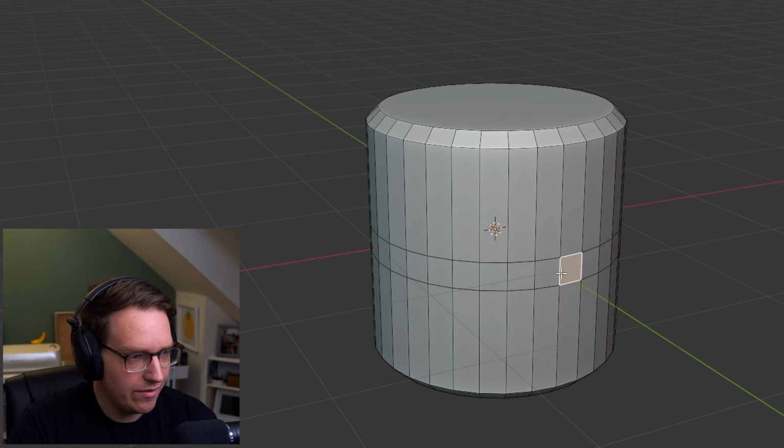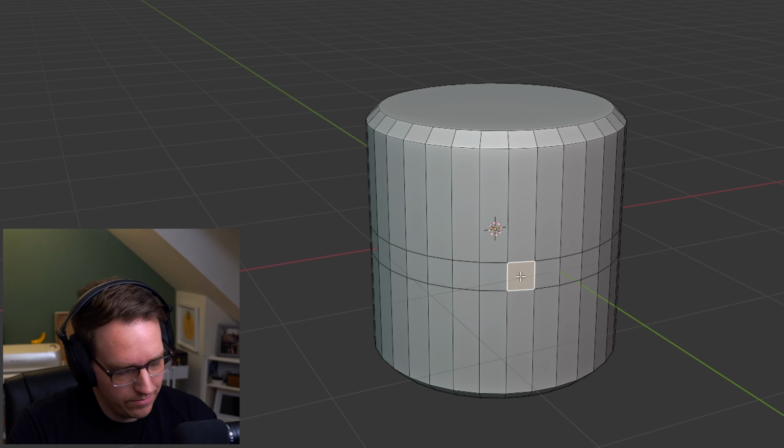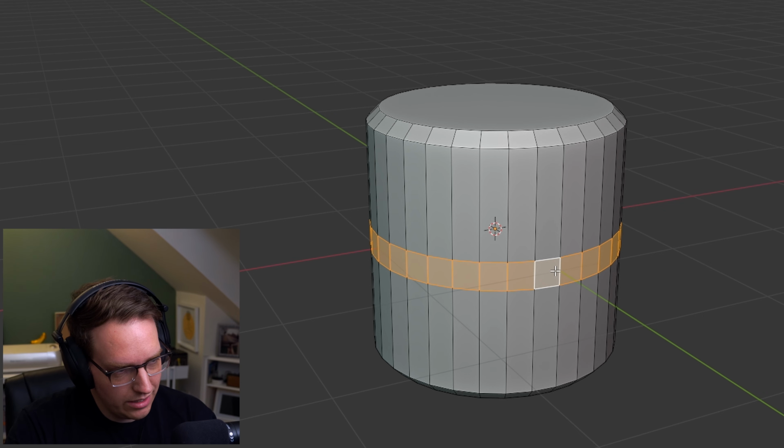So by doing different operations, I can add or refine my geometry on my primitive. Before I didn't have the ability to select in here because it was just one long polygon face, and now it's actually 3 faces. So now while I'm in face selection mode, I'm going to select this face right here. I'm going to hit Alt and then left click next to it, and it's going to do the same thing that the edges did, but we're in face mode now.